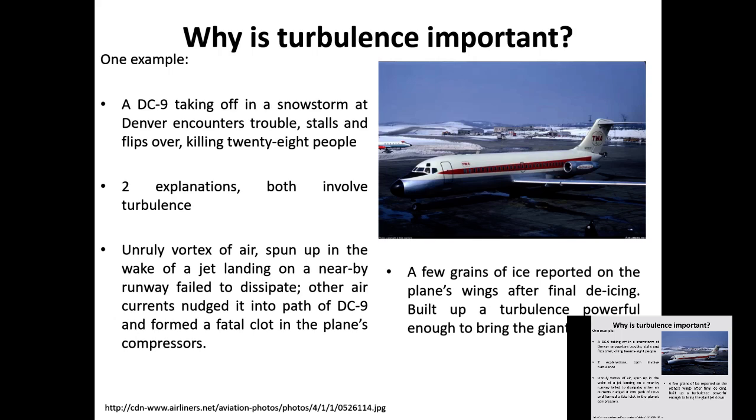But when you get to the end of the car, there will be these streamlines. They detach. Okay? If they detach, what will happen is there will be a vacuum created here. Therefore, what you really want to do is you need turbulent flow here at the back, and in the front you want laminar flow over the body. At the back you need turbulent flow so that your drag from behind is less.